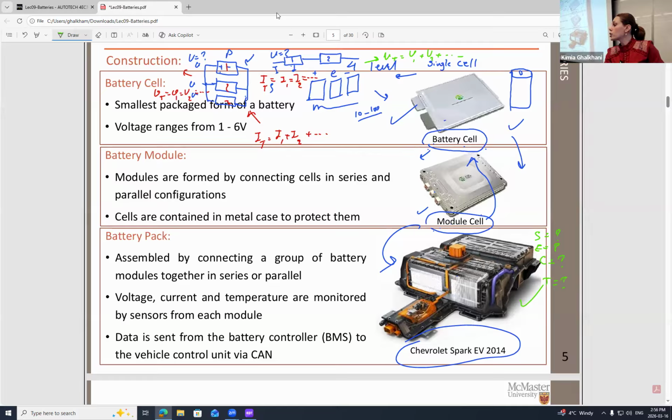If I'm having a larger pack, definitely trouble means I'm having too many unnecessary batteries or low quality batteries. That's why I'm using too many cells, or I would say modules, in order to come up to that certain level of energy. Therefore, cost is impacted, troubleshooting is impacted, quality is impacted. So it's really important to pick the right one, the lighter one, the one that has more durability, more safety, and stability, and so many other factors. So far, everyone okay? Any question?